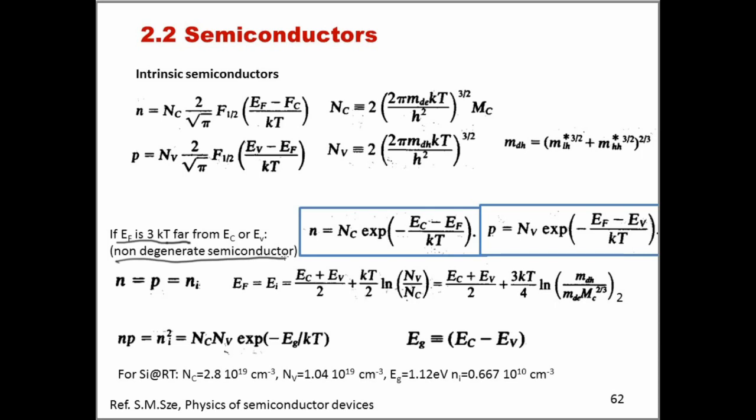Okay, so it's still silicon with a little bit of impurities, and not impurities with a little bit of silicon. That's the point. So in this condition of non-degenerate semiconductor, we can demonstrate that the formulas we've just seen can be simplified, and they take this form here, and the density of electrons is calculated using this formula here, and p can be calculated in that way.